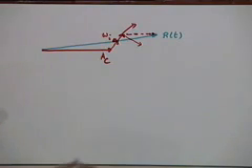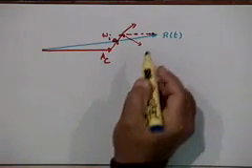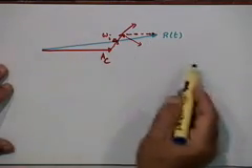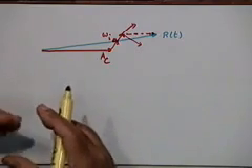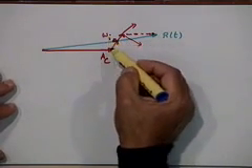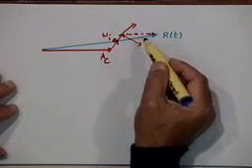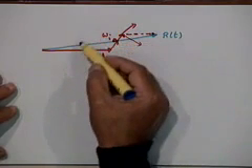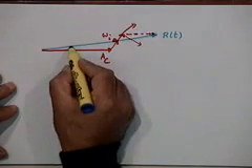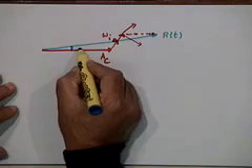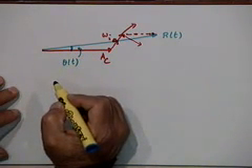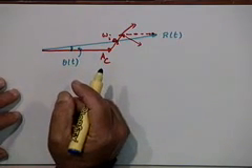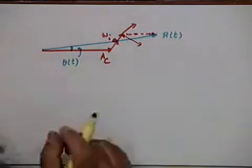So one of the things that you can see, that now the resultant phasor is not along the carrier phasor. Therefore it is not undergoing only amplitude variations. Amplitude variations will be there as all these phasors rotate. As this rotates and these two rotate, the amplitude also will keep varying, right? But in addition, there is also a phase variation, right? Theta of t. So these two variations are being introduced.